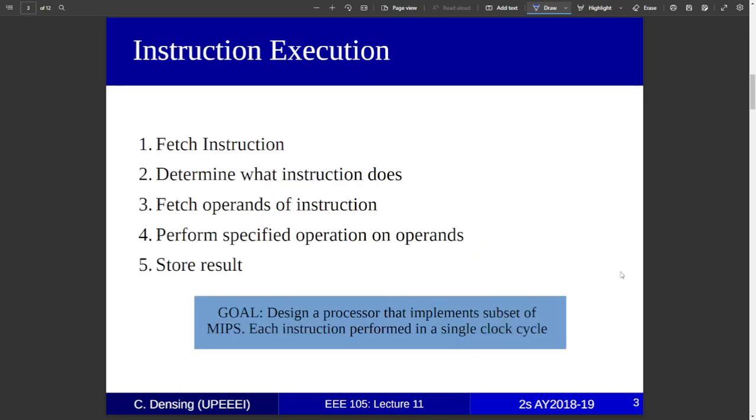So the single cycle data path is basically the computer. It's already a processor. How I think personally about a processor is that you have states that are determined by the internal registers or the internal memory files of the computer, and then you have an instruction. The instruction is the input, and the instruction forces the computer from one state into another state, and then yet again into more states once you read more instructions.